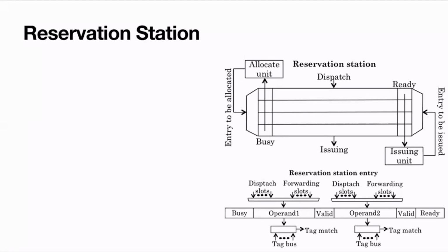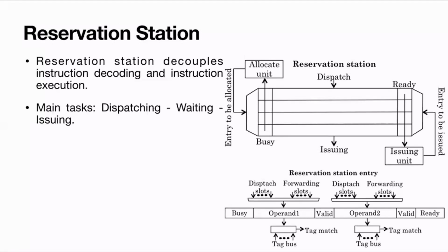Some people will think that maybe it's a good idea to consider a centralized reservation station. And some may think that no, it's better to have a reservation station for each type of operation. Maybe you have one reservation station for add operations, one for multiply operations, one for control instructions, and so on. So you can have those, and each reservation station is tied to the corresponding functional units. So that is one thought of design.